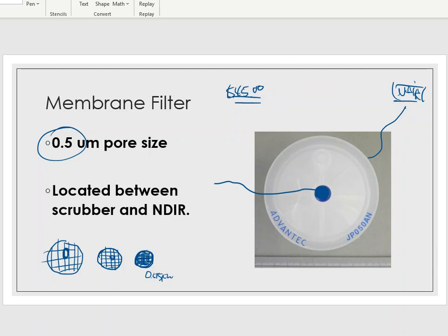You just take the side cover off of the instrument. This is one of the pieces that's up front and center. You just unsnap the front, unsnap the back, put your new filter in, and then snap the tubing lines back on the front side and the back side of the filter yet again. That's all that you have to do.